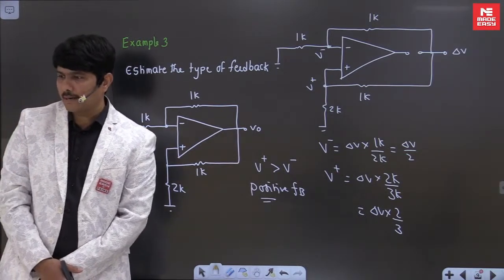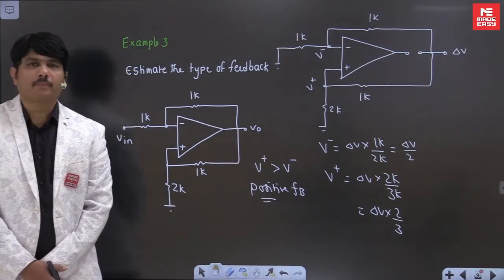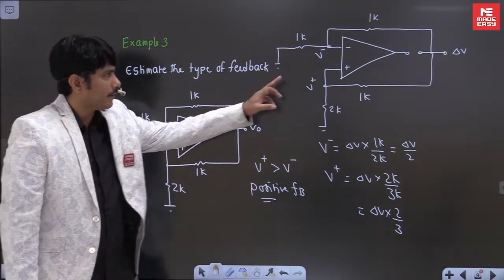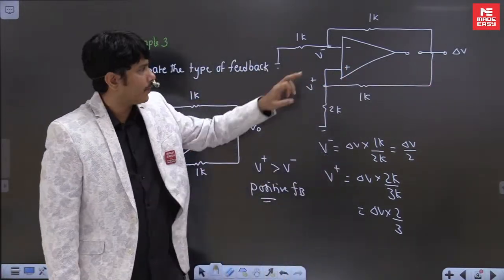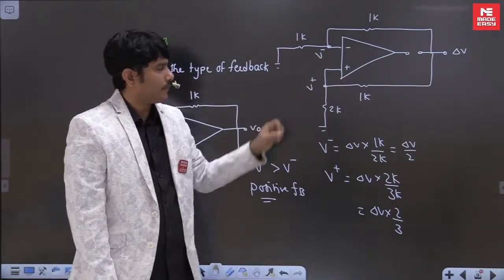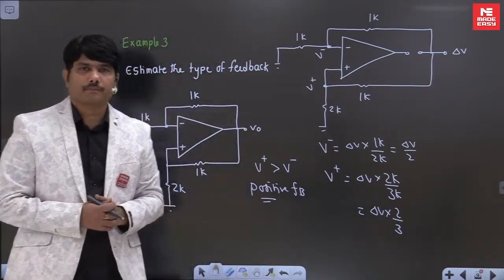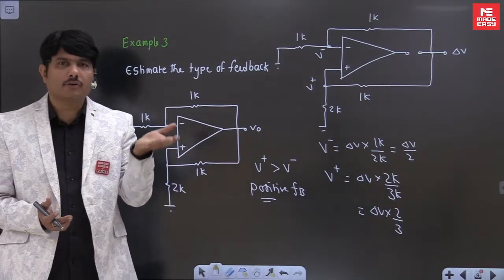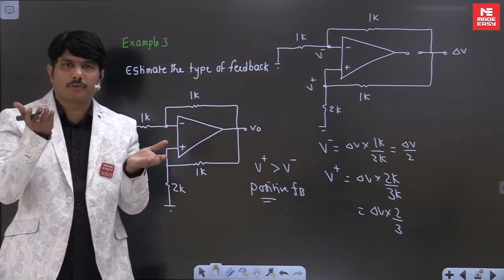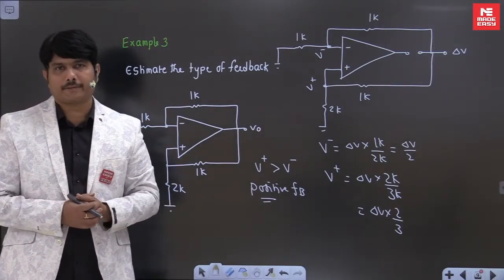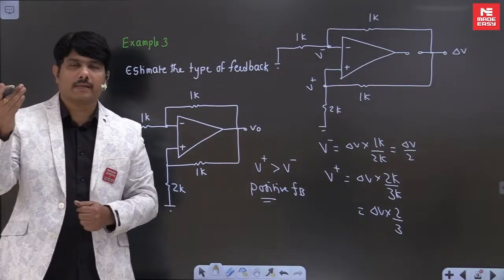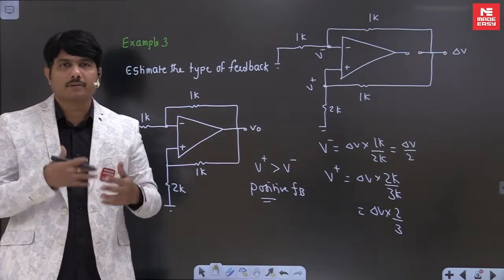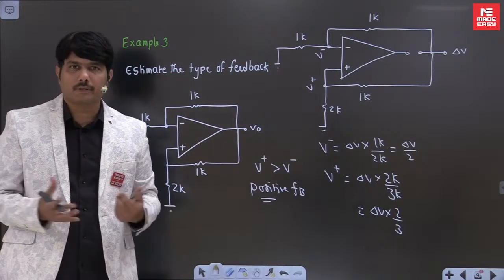Verma, what is the logic behind your trick? There is a simple logic, nothing more. Here when you break the output, I have given some common voltage for the negative feedback side and for the positive feedback side, such that we can verify whether the negative side is dominating the feedback or the positive side is dominating. Taking a common output voltage, assuming that del V is increasing slightly, we started the testing for that, nothing more than that.